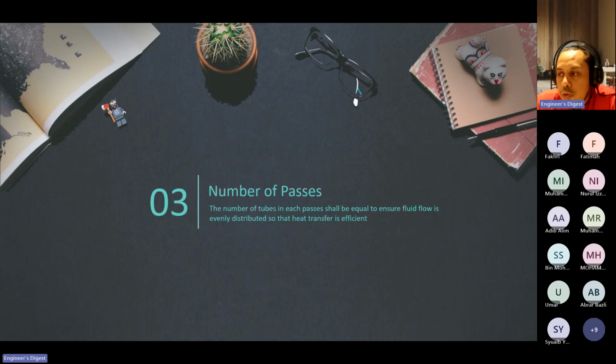And from the simulation, either by Aspen or by HTRI, they will know, if we plug so many tubes, what is the future effect to the heat duty of the heat exchanger. So number one, there is a 10% margin, we can use that. But number two, we still need to get advice from the PED or process side. They will be able to check the outlet temperature and do calculation from there.